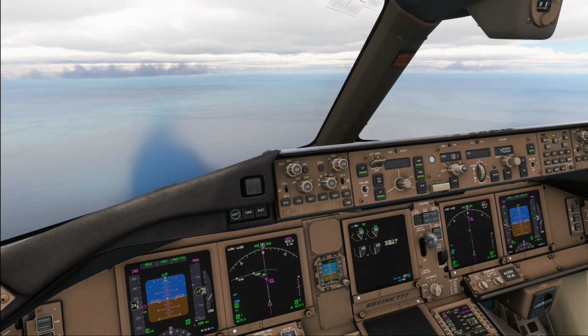Now, once we're at least 300 feet below the missed approach altitude, we are going to set the missed approach altitude on the MCP. Ensure that the missed approach altitude is really set only once you are at least 300 feet below it. Otherwise, VNAV might try to capture the altitude and you are basically out of the approach and you can start a new one. So, try to build in some distance to altitude checks, which normally the pilot monitoring would do for you.